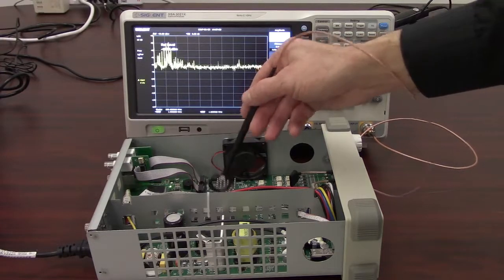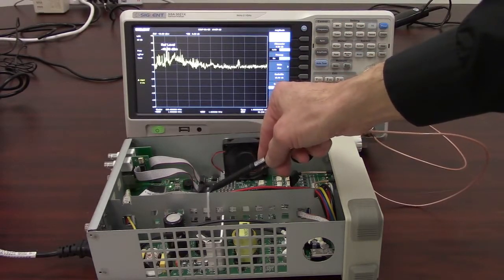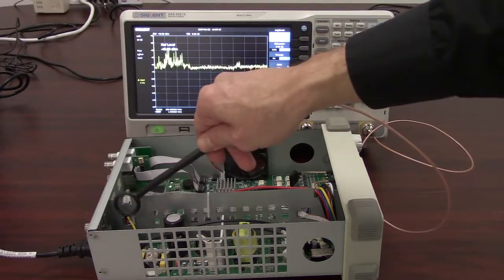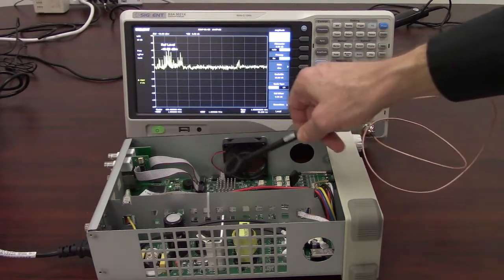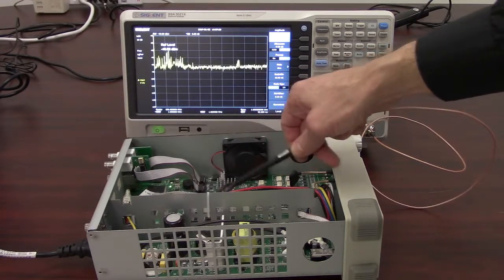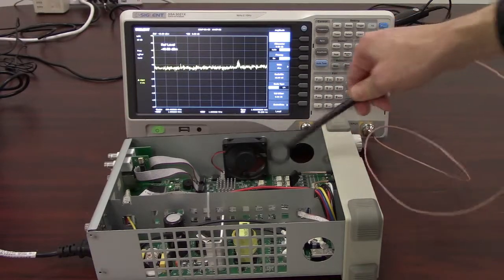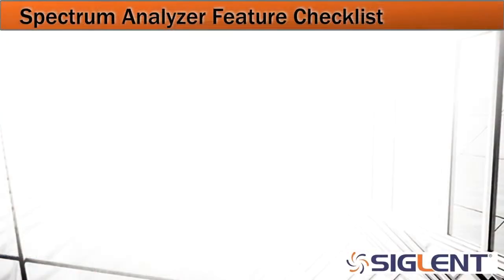This isn't a direct indication of a failure from an electromagnetic compliance test standpoint. Again, the near field probes are typically used for troubleshooting, so you may already know where your issue lies, and now you can sniff out, they do also call them sniffer probes, the areas that may be most problematic on your design. In that way the spectrum analyzer can help you with the use of these probes to find those particular problem areas and make corrections accordingly.